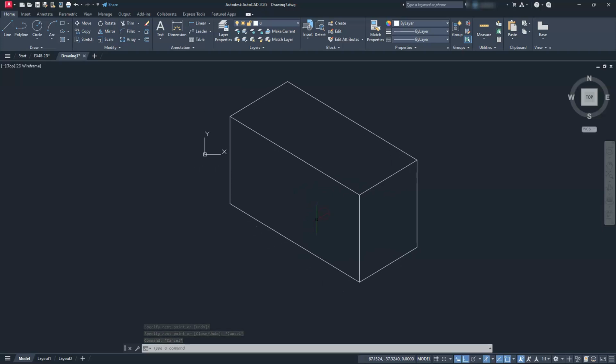Now we have some other stuff that is happening here, and we're going to just start whittling this off, right? So I'm going to assume like this is a three-dimensional part, and I'm just going to start creating these circles and things that I need. So starting here at the isometric left, let's go ahead and switch to that. I'm going to go ahead and create this isocircle. So I'm just going to type in EL, enter, I enter. I need to specify the center. For right now, I'm just going to specify the center right here at this midpoint.